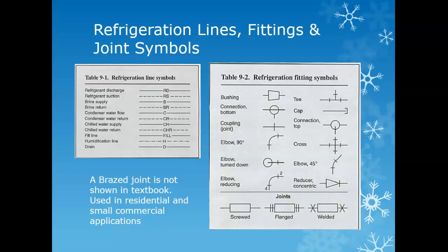So most of the time with those kind of joints being smaller, welding would be all but impossible. Simply because the metal would get too hot and start trying to melt into itself. So most of the time what we tend to do with things in your house is we do a lot of brazing, soldering, things like that. Because it still creates that permanent connection, still creates the seal.